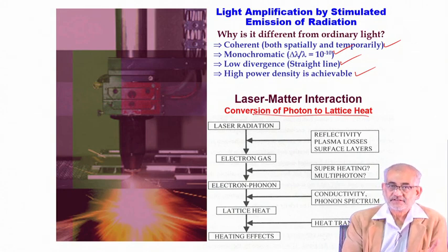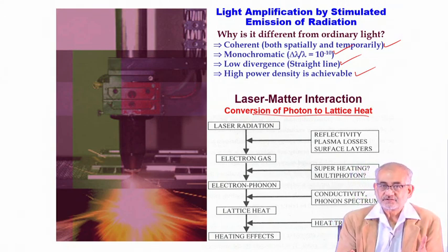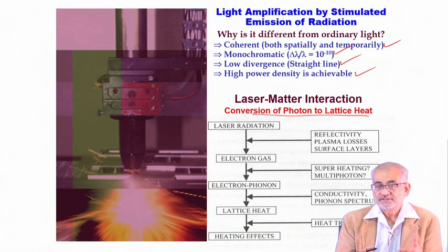So metallic and non-metallic, to make it much simpler. Metallic materials will have a free electron cloud available on the surface. So incident electromagnetic radiation or laser will always have an opportunity to interact with the free electron cloud, and the majority of the incident wavelength will actually have the possibility of getting reflected back.